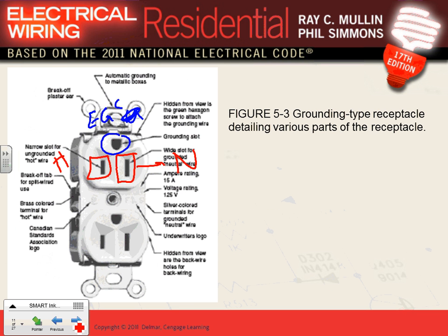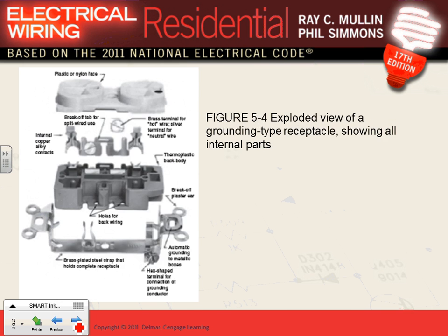You guys can appreciate that you can drive across the United States and plug into any 15 or 20 amp receptacle, and you can guarantee that your plug is going to match the receptacle, right? That's where NEMA becomes a big deal in configuration. This might not make a whole lot of difference, because we all grew up with this one, so it's not a big deal. Now imagine having a 50 amp receptacle. Do you think it should look like this, right? So for all these configurations, NEMA came up with different configurations, guys, for different amps and different voltages. Which means a plug of configuration 1 cannot fit in a receptacle of configuration 2. Anybody know why? If I can plug this one in a 240, I'm going to burn my equipment, for safety reasons. Okay, so we got that one.